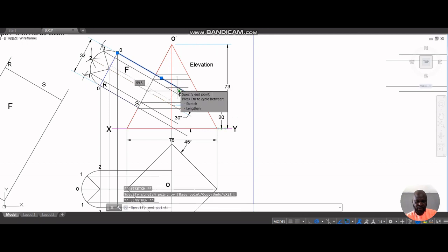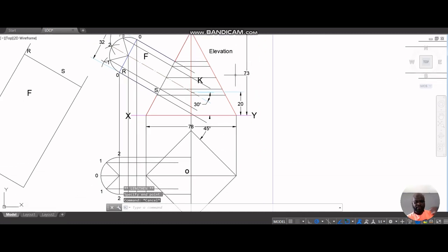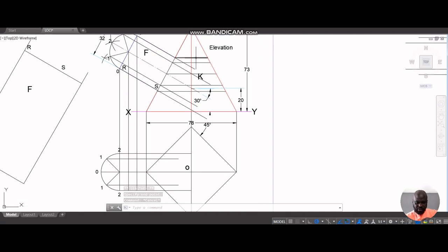So that's too much interference. So taking that short, these are the cutting planes, points of entry of the cutting plane. So we'll trace that point on the plan view and see where it intersects these cutting planes that we also have. The same cutting plane on the pipe and the same cutting planes that we have in plan view. So let's do this quickly.